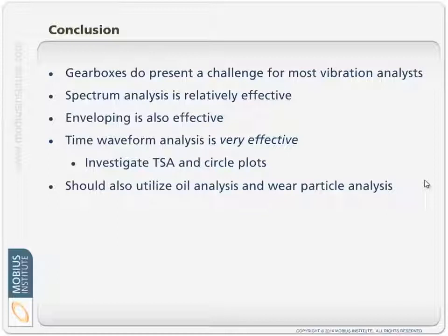Think about the failure modes and the PF interval to make sure you're taking your measurements frequently enough. And also think very carefully about oil analysis to make sure it's being lubricated correctly without contamination, and wear particle analysis, so that you can detect those particulate contaminants but also detect any wear that's going on.